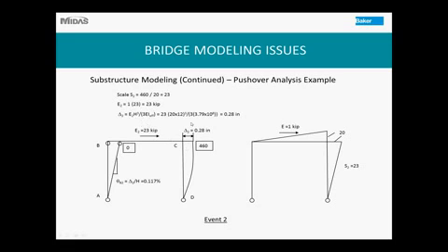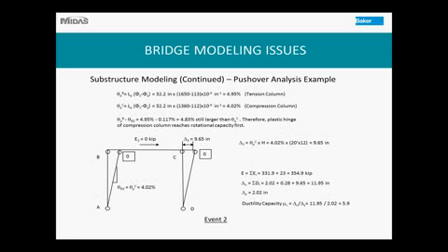And then you calculate the elastic lateral displacement for this event 2 again. This time, you only have one column effectively resisting the lateral loads, so your stiffness drops down to 3 EI effective divided by H cubed. You calculate that again, and you get 0.28 inches. Now, after this event 2, both columns, B and C, have reached the plastic MP. So the bent has formed a mechanism, and it can collapse, but it can still rotate, because the plastic rotation capacity of B and C has not been achieved.